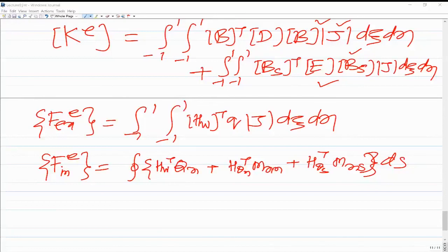Theta x and theta y are independent, so there are 4 degrees of freedom for theta x and 4 degrees of freedom for theta y. So for each variable we have only 4 degrees of freedom in the element, and that is why 4 shape functions. In the classical case, corresponding to w itself there are 12 degrees of freedom, so that is why 12 shape functions. When we talked about the compatible rectangular element for classical plate theory, we had 16 degrees of freedom corresponding to w itself, that is w and its derivatives. So there we had 16 shape functions.